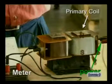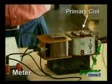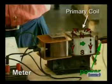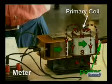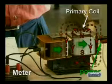When the switch is closed, current starts passing through the primary coil. Remember, a current passing through a coil will produce a magnetic field. This magnetic field will magnetize the soft iron core that passes through both coils of the transformer.